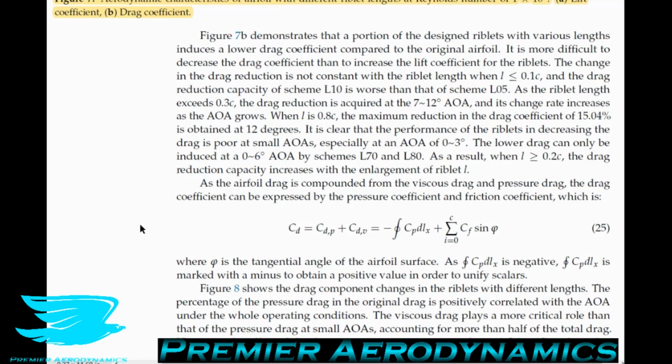So the reason why this is important is because now we can understand how the drag comes about on this airfoil. I just want to touch briefly upon three-dimensional airfoils, because now we get into more practical applications, as most applications do use a three-dimensional airfoil. In this particular case, the drag is not just made up of the pressure drag and friction drag, but also something called the induced drag. The induced drag is visible as the wingtip vortex. So that's a very easy way of understanding what that is from a conceptual point of view.